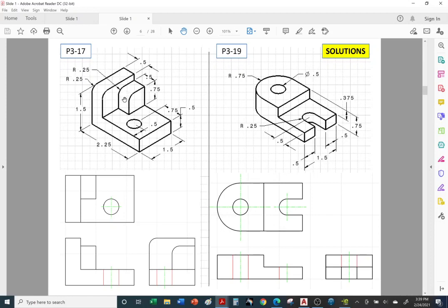Okay, so here it is, the isometric view. We have the front view. So if you're standing here, this is the front view. Right side view. Come back to the front, fly over the top, and you'll get the top. So here it includes the center lines. So remember I mentioned anytime you see a circular hole or a semicircle, half circle, you're going to draw the center of that arc or circle.